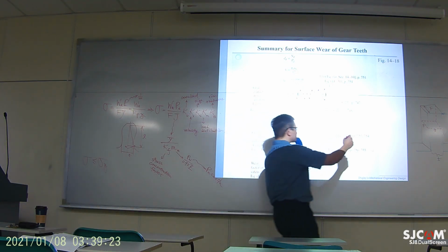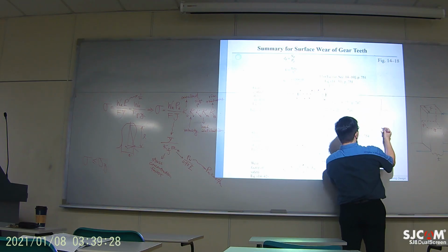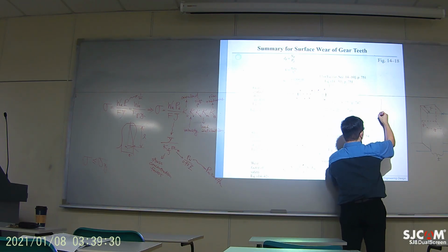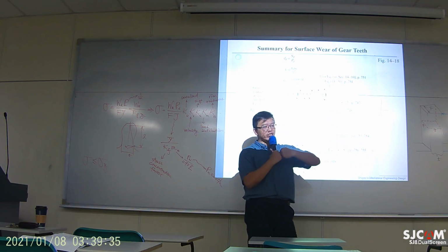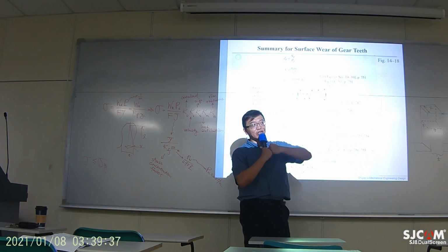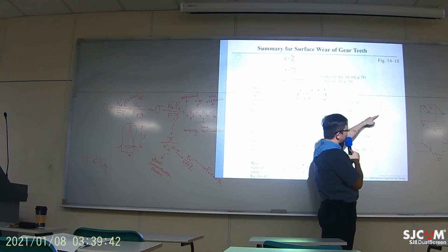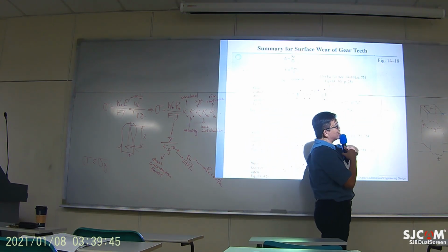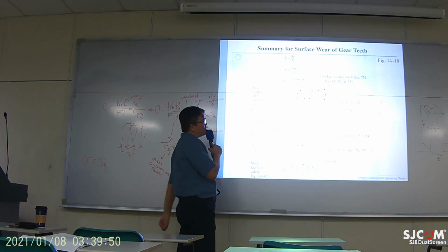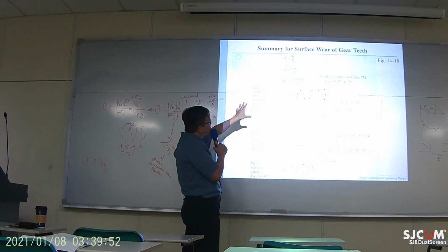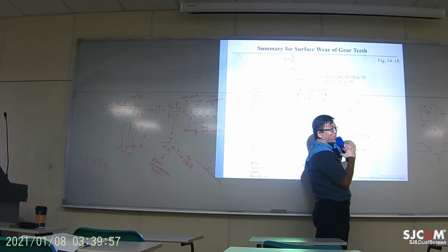Whenever you have two geometries in contact with each other, the objects are just pushing each other really hard. If you pay attention to that point, the stress right at the contact point is actually higher. It's concentrated at that area.